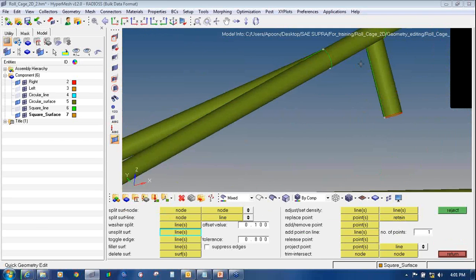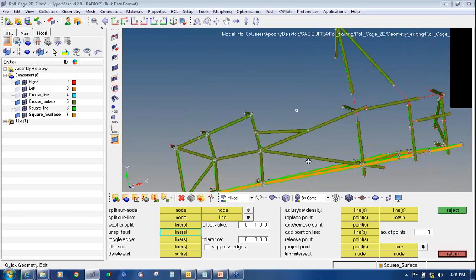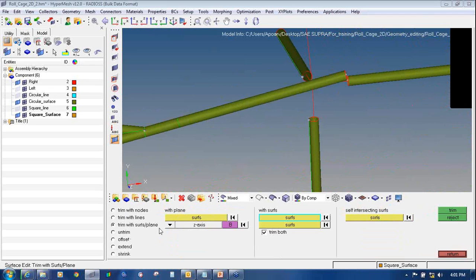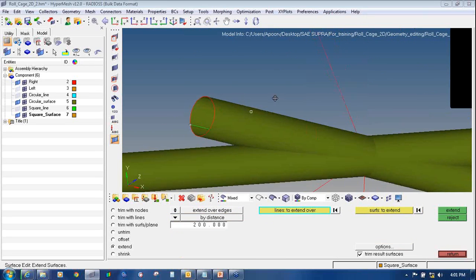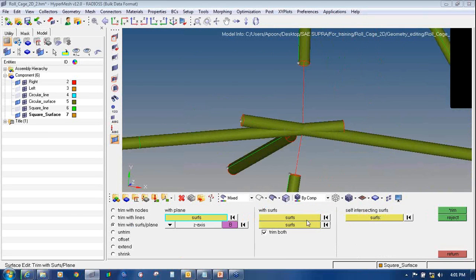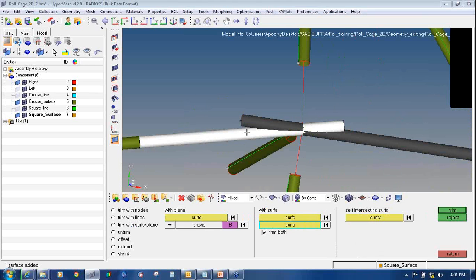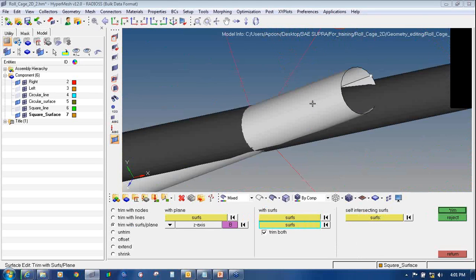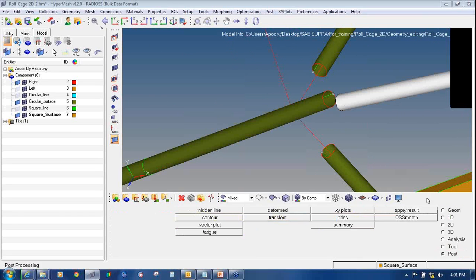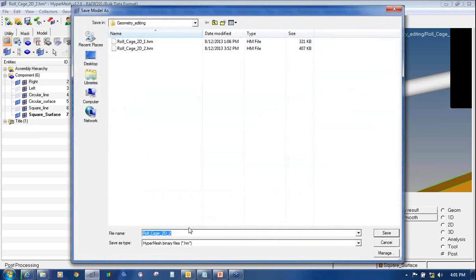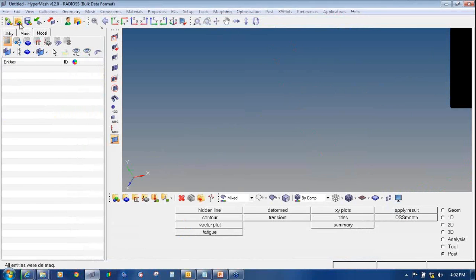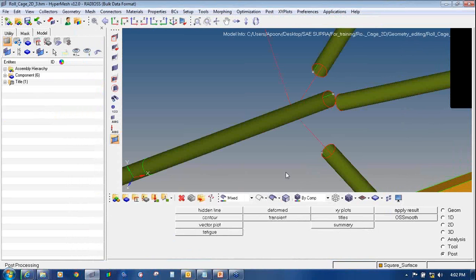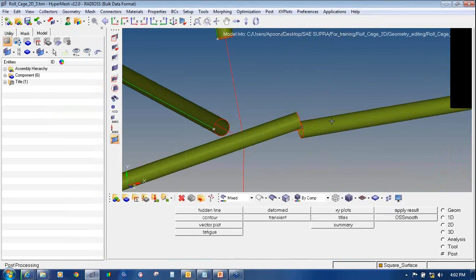There are some points where the splitting lines are not perfectly done. That also I will show you, how to split them perfectly. So one by one, all the joints you have to just clear that, or Shift F9 again. Always save the file in the different folders, so if that is not working properly, you just save it and again open it.